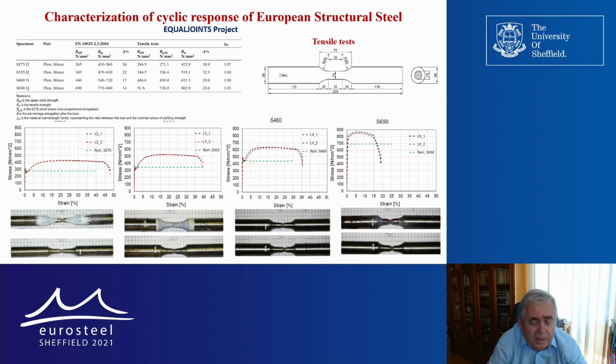But there also are those overstrength components which usually are designed to remain elastic during the earthquake, and it would be the right place to apply high strength steels in these seismic resistant structures.